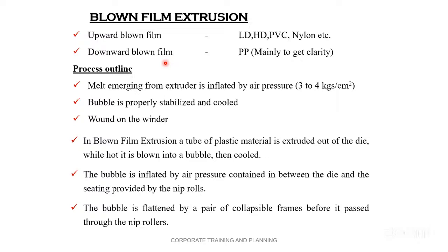So PP having low density. Yes, pardon, please. You see, correct. Polypropylene doesn't have melt strength. Its melt strength is very less, whereas the melt strength of the other polymers is very high. But this polypropylene easily shows shear thinning property, and that's why.